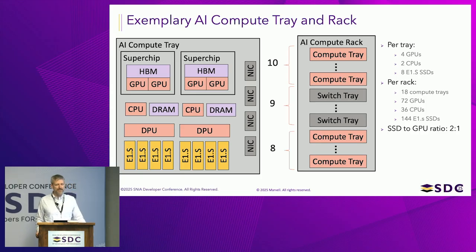That's important from a performance perspective, because if you consider that one GPU has 16 PCIe lanes available for performance, that's how you can saturate it. But then one SSD has only 4 lanes, so you have to look at that ratio to see how you design these SSDs so that the performance is matched relative to the GPUs, so that the GPUs don't remain idle.